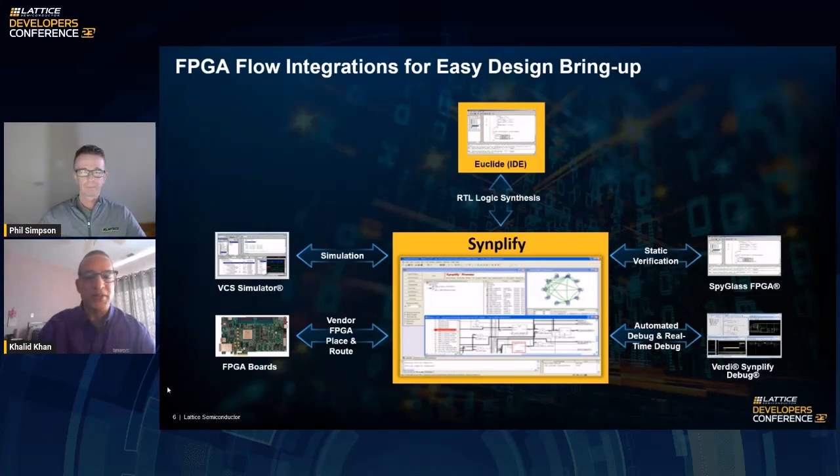The Identify instrumentation debugger tool provides an easy-to-use interface to probe any hierarchical design signal and dump out waveforms from live hardware. And the Verdi debug environment allows users to compare waveforms and correlate live hardware signal values back to the original RTL signals for comparison and verification purposes.